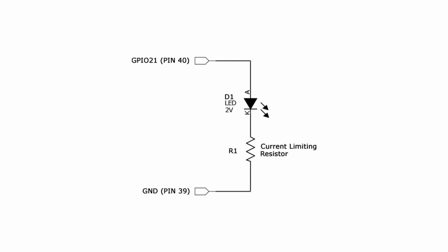So what we need to do is figure out the resistor values that we need to use to produce the following currents: 2 milliamps, 5 milliamps, or 7 milliamps, within the maximum drive capability. The LED can handle up to 20 milliamps, which is what is stated in the data sheet. However, the Raspberry Pi, depending on how the port pins are programmed, cannot supply that much current. So we're going to limit it to 8 milliamps maximum.